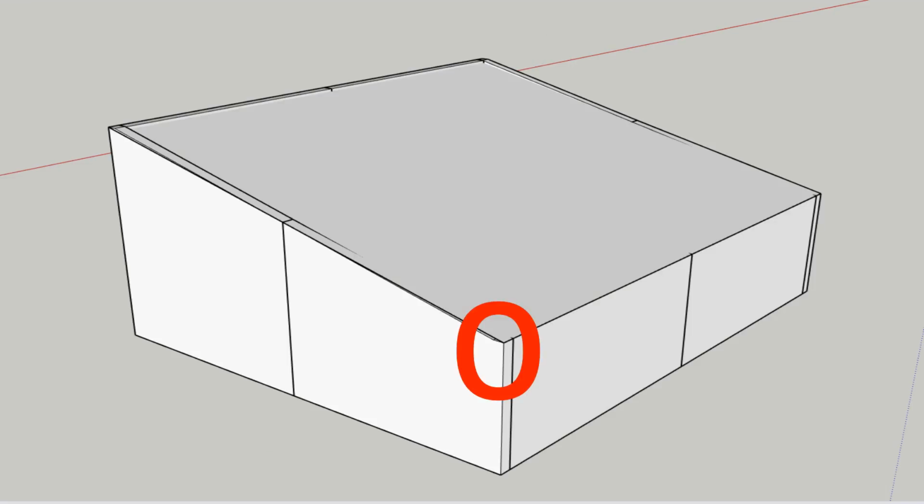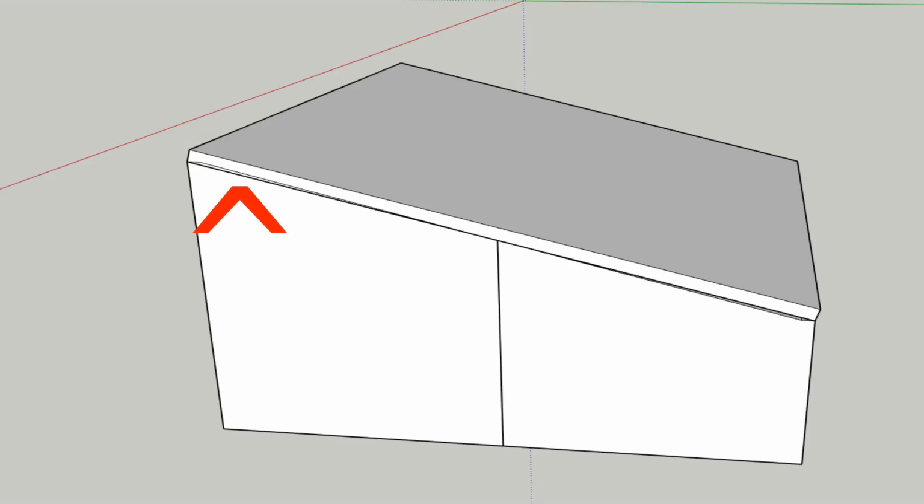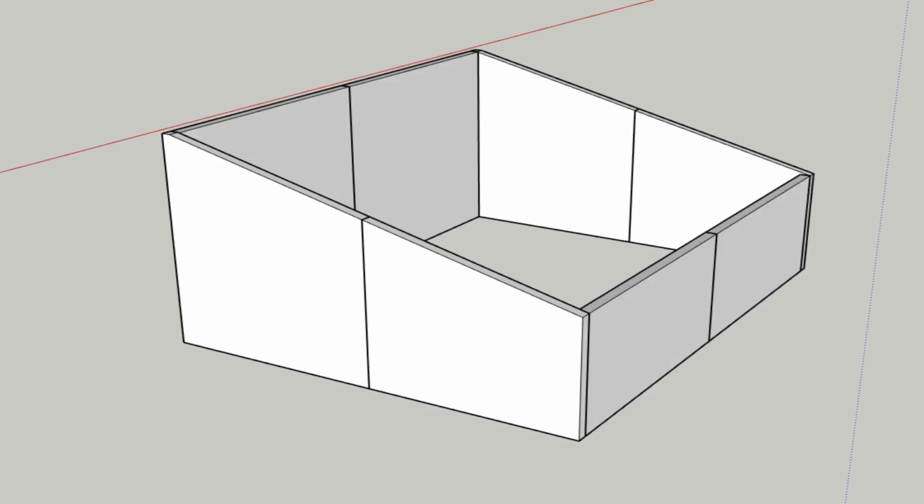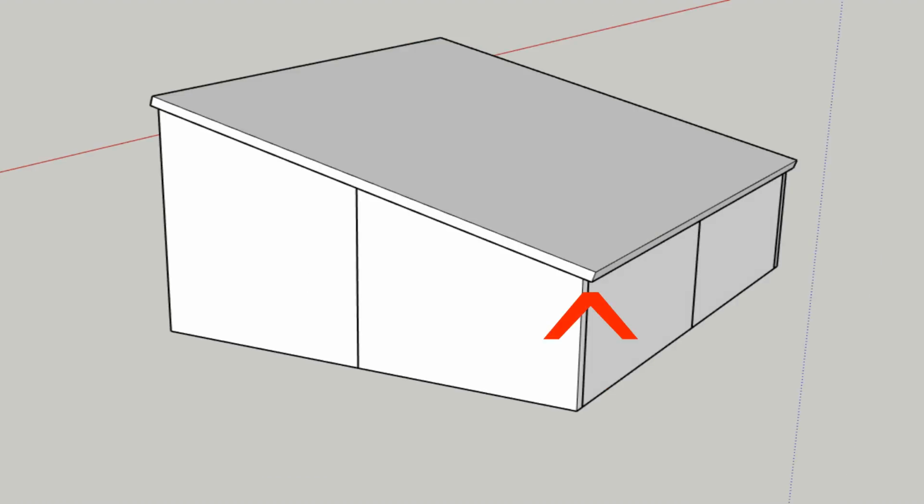If we apply the acrylic on the roof from corner to corner, when assembling, we end up with something like this. If we fix it by moving it on top of the structure, the problem becomes like this. However, a much better solution is to move the front and back pillars a bit more inside the side panels and not have the strange lip anymore. Also, have the roof a tiny bit longer in order to provide better coverage for the wooden panel against rain.